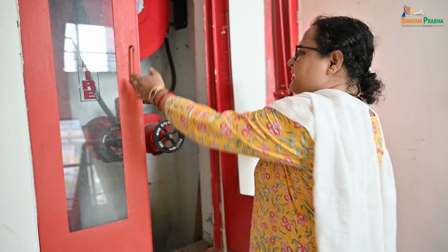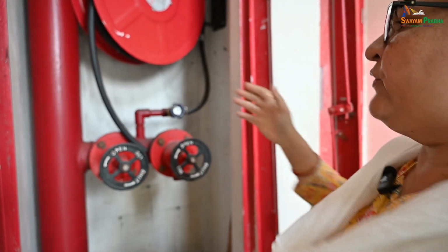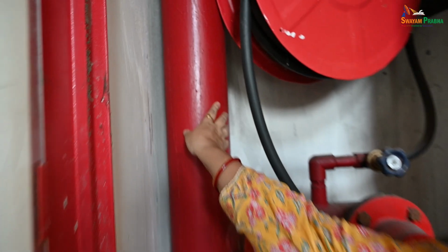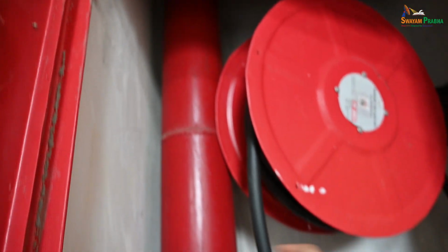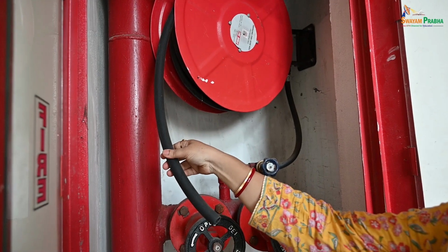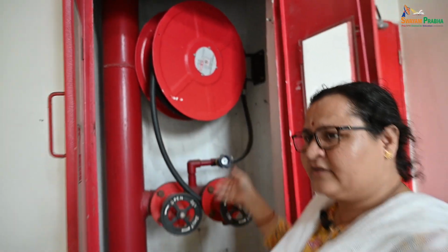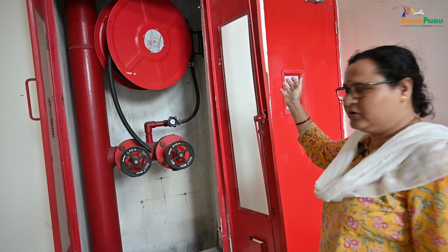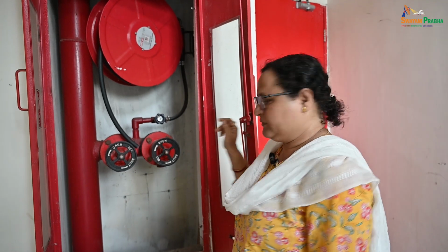Considering that this particular floor was on fire, what can the firefighting personnel do when they come to this floor? First, from the bottom, that is the ground floor, they will access this floor and open this space. If you remember, this is the pipe which was coming down from the rooftop, and here is the hose reel through which, on pulling, the hose can be drawn into this floor, and they can attend the fire to control it.